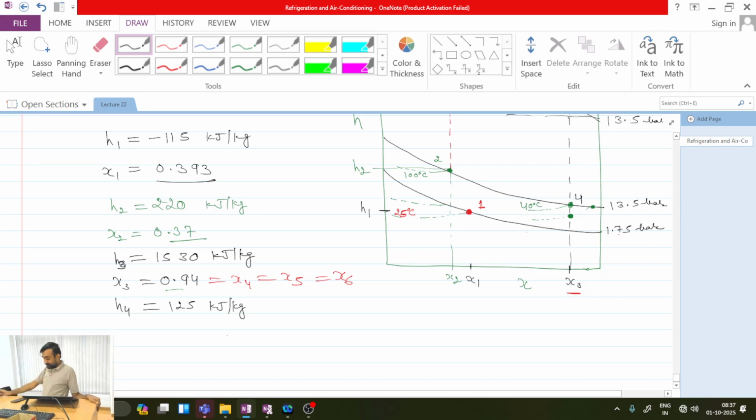Okay, and interestingly, one can also give you the question that if state 4 is a saturated state and only pressure and composition are known, can you determine its temperature? Of course, if you know this point, then you can determine the line passing through it. So temperature you can locate as well. So temperature at present is redundant data. Okay. Let's go to state 5.